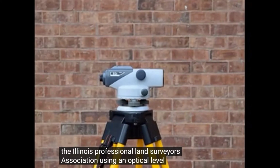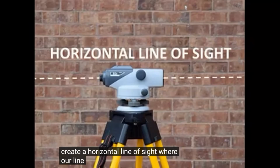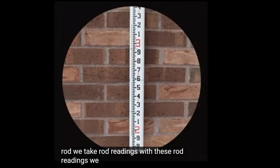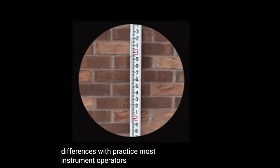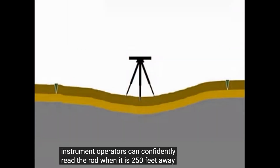Using an optical level, we create a horizontal line of sight. Where our line of sight intersects the level rod, we take rod readings and compute elevation differences. With practice, most instrument operators can confidently read the rod when it is 250 feet away.